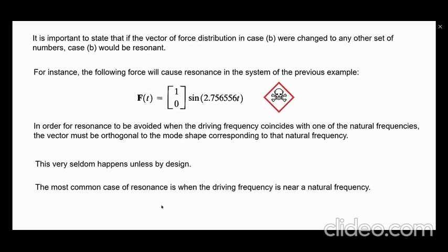And therefore, the most common case of resonance is when the driving frequency is near a natural frequency. Unless that f is selected in a very special way, you may not have a resonance case, but generally speaking, that is not the case. And if your natural frequency matches the driving frequency, unless it was done by design, you should expect resonance, just like in a single degree of freedom system. And that takes care of the presentation for today.